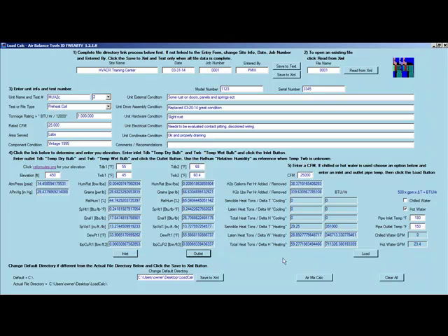So now we have an inlet, outlet, and now we have our grains converted into pounds per hour and gallons per hour, added or removed. So in this case, this machine would have to output about almost 600 pounds per hour to be able to maintain the 65% RH under this condition.